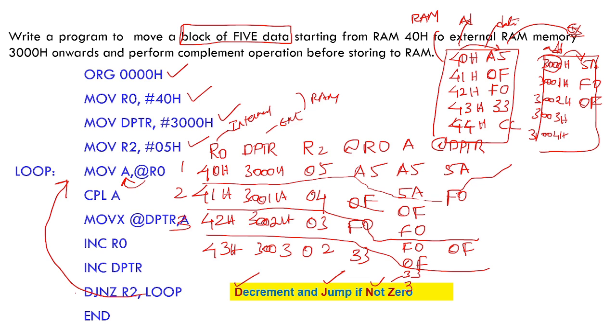If you see 8421, 0011, 0011, this is 3, 3, 33. If you take a complement, 1100 1100, so you will get CC. So after updating this, the accumulator holds CC, right? So it is complemented and stored in the accumulator.